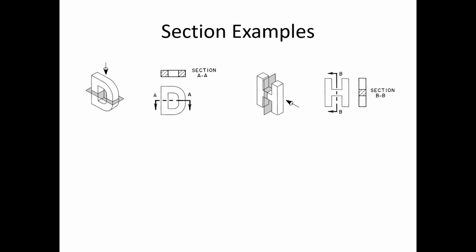If you're working on round parts or shaft type parts, and you create a cutting plane and you project your section view, and it looks like exactly the same shape as the view you put your cutting line in, you put your cutting line in the wrong view. Right? It should be a different shape than what you started with. Okay, so try to explain that. But we still have a cutting plane line